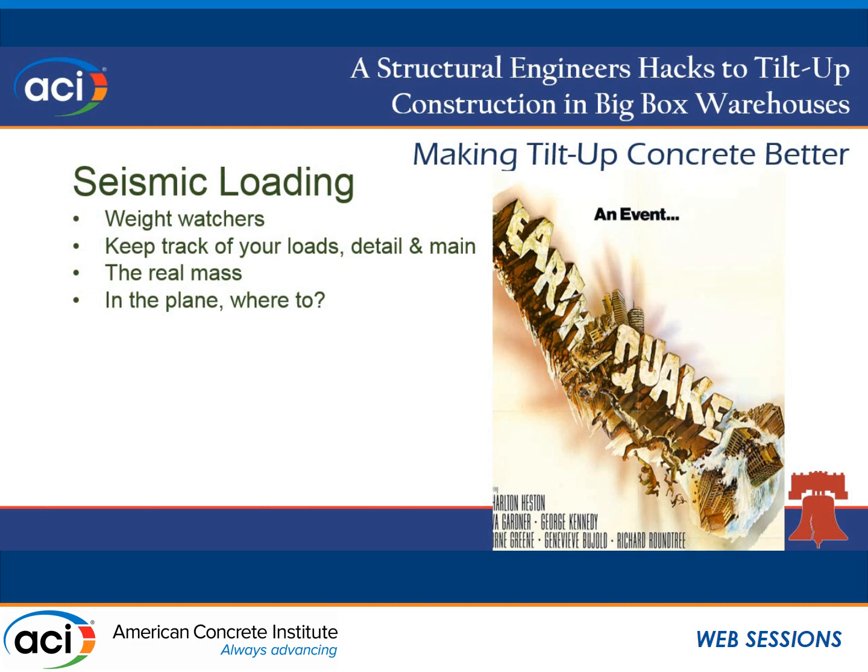So, in designing for a seismic event, the first thing I try to do in trying to figure out the start of my building is figure out what my panel thickness is going to be. Panels are going to be about 30 to 50% of my overall roof mass. So accounting for that out-of-plane load, I've got to be careful what I'm doing. Now it's a fight, right? When you want to do the connection design, when you're trying to do the embed, you like to have a nice thick hunk of concrete to grab a hold of. But every inch you add to that panel is just going to increase your base shear and give you more to deal with. Especially in seismic, you'll find your in-plane overturning can really be a pain in the butt.